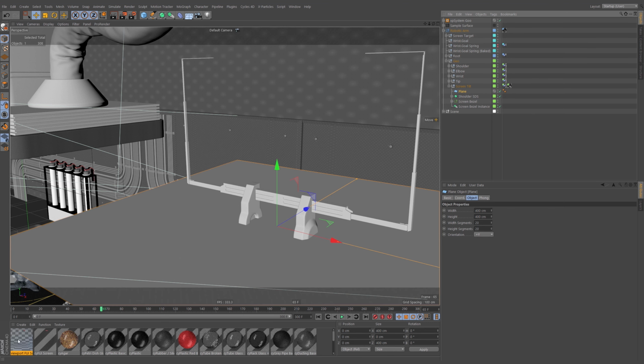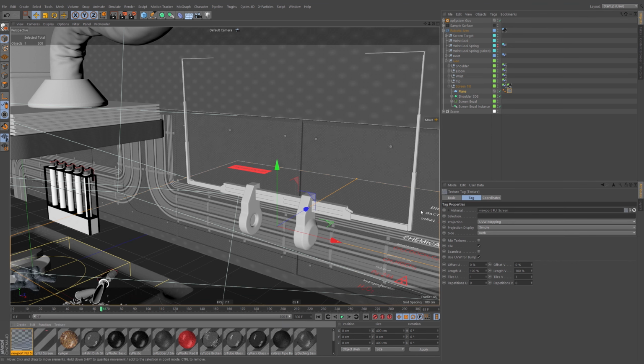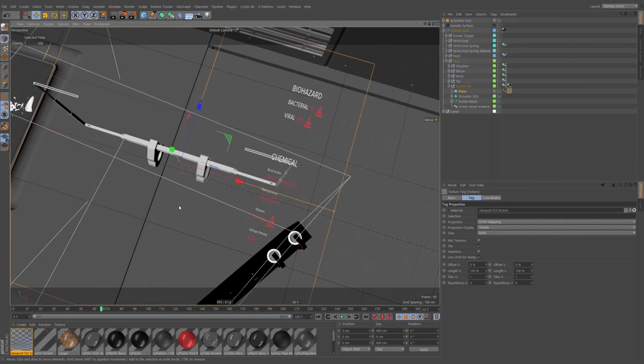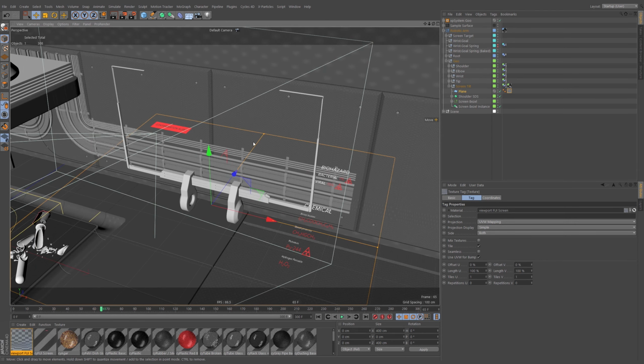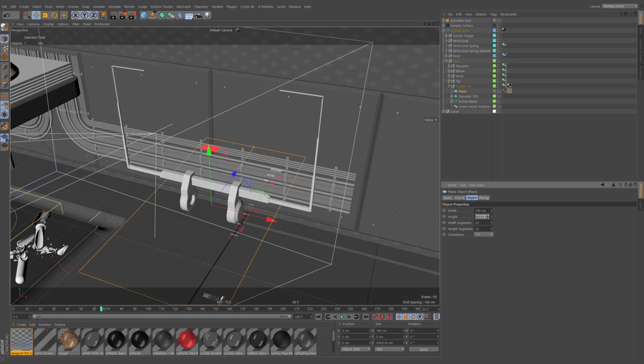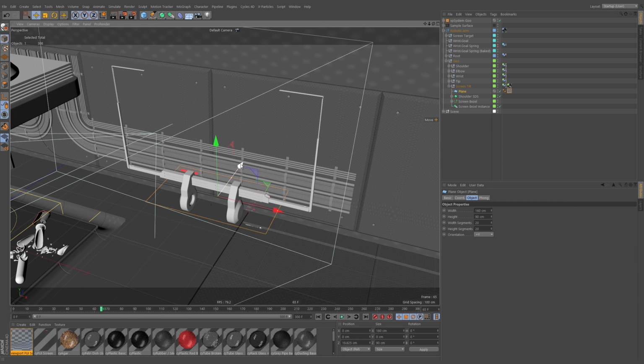And then let's just drag our material on, just so we can see what it looks like and see the orientation. And you can see we've got these sort of weird words and things on there, but it's just a framework for us to play around with. You can create your own here, of course. And I know it's roughly 16 by 9. In fact, I know the texture is 100% 16 by 9. So let's change this to a ratio that's correct. So that's 16 by 9.